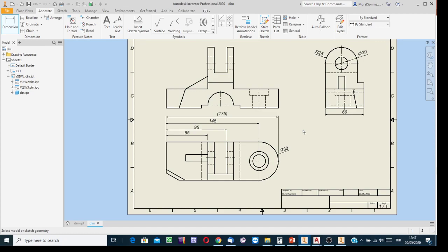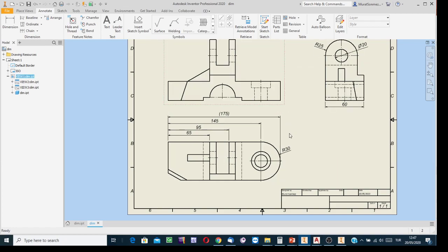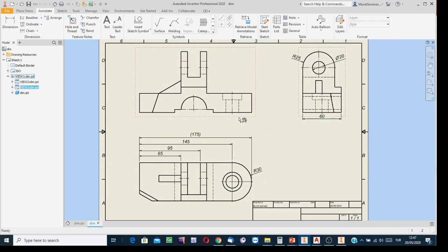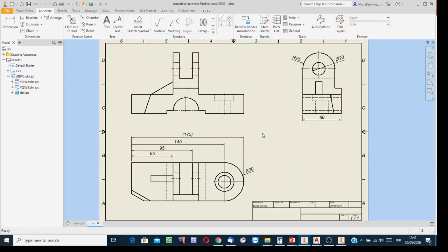Well, in AutoCAD, you know, whenever you perceive that the space between the views you initially had is not sufficient for showing the other necessary dimensions, then you apply the move process, to be able to move not only the projection but the associated transfer lines. It takes a certain time, but in Inventor it is quite easy. Press the escape button, finish any running command, and then hold the base view with a click, and then, making such trials, shifting the views, make the space between the views sufficiently large, yes, and then continue.